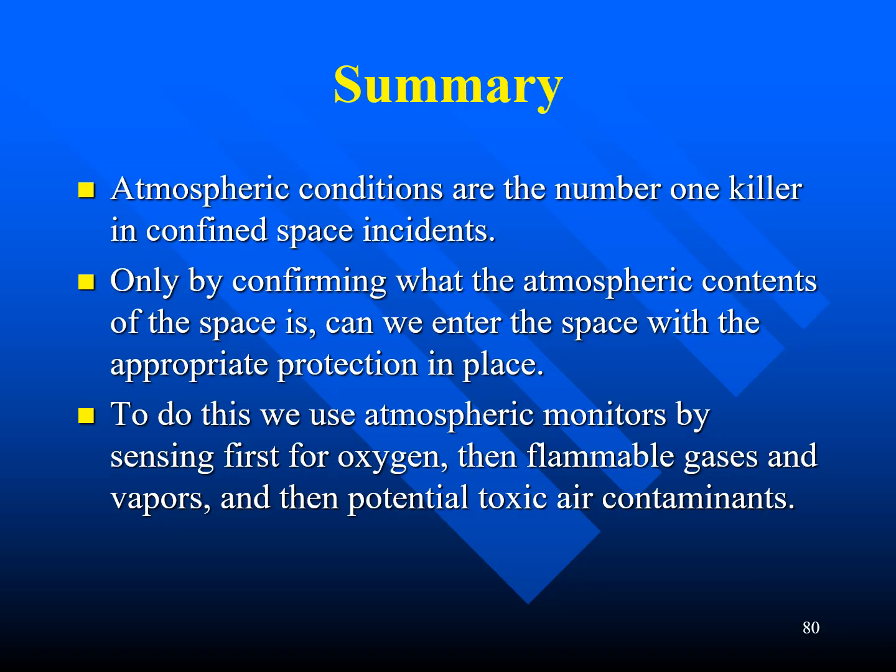All right, let's summarize this lesson. Atmospheric conditions are the number one killer in confined space incidents. Only by confirming what the atmospheric content of the space is can we enter the space with the appropriate protection in place. To do this, we use atmospheric monitors by sensing first for oxygen, then flammable gases and vapors, and then potential toxic air contaminants.